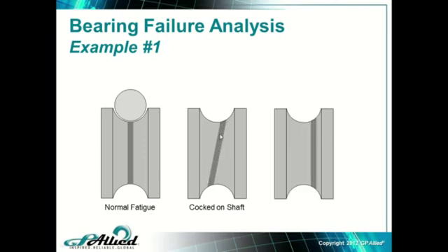Another failure pattern. He brought me another one that looked like this. Those of you who are watching, it should be in the center, but it's pushed off to the side. Well, this is called axial loading, and the particular root cause of this one was they took 2 bearings out of the box. Each bearing had an expansion ring. They didn't know that for 2 bearings on the same shaft, you only need 1 expansion ring. The other one you can throw away.